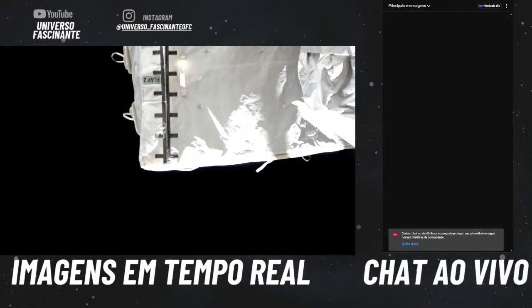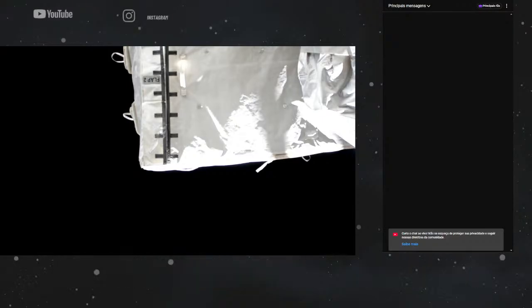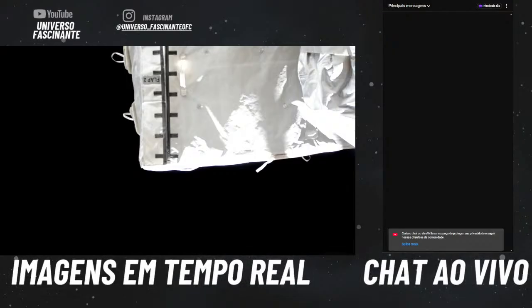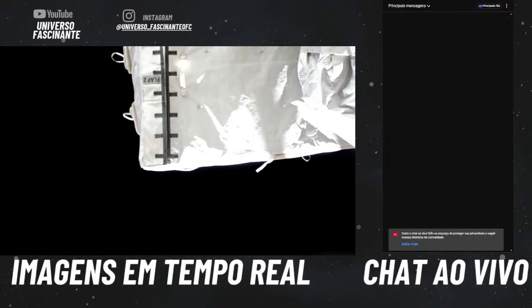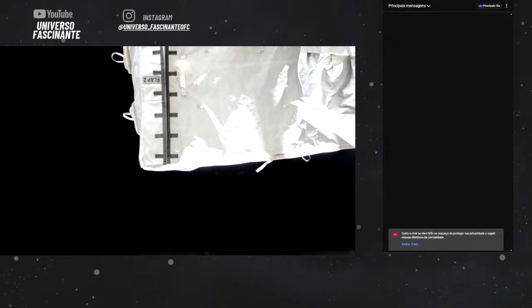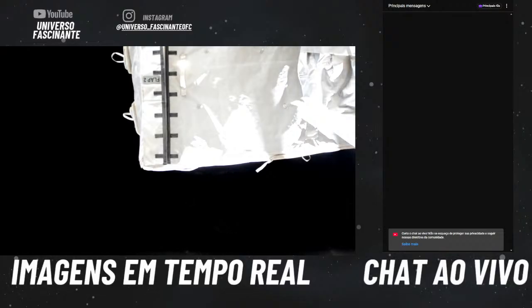the big burn. That'll be the deorbit burn that is scheduled at 10:09 and 46 seconds p.m. Central Time, 11:09 and 46 seconds p.m. Eastern Time. That burn, which is basically a braking maneuver, it's a retrograde burn of 4 minutes and 42 seconds in duration to slow the Soyuz down by 128 meters per second, allowing it to basically fall out of orbit on its high-speed entry back into the Earth's atmosphere.